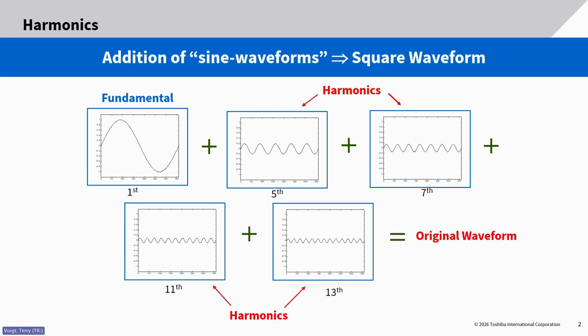So essentially, harmonics are a bunch of little waveforms. You have the first fundamental waveform, as you see in the presentation. Then you have little harmonics too, so 5th, 7th, 11th, 13th. Those are examples. They go up through a very, very high number, so high order of harmonics. A harmonic spectrum is another fancy word that gets used in this topic as well. But essentially, everything gets added up, and then we get a final waveform.